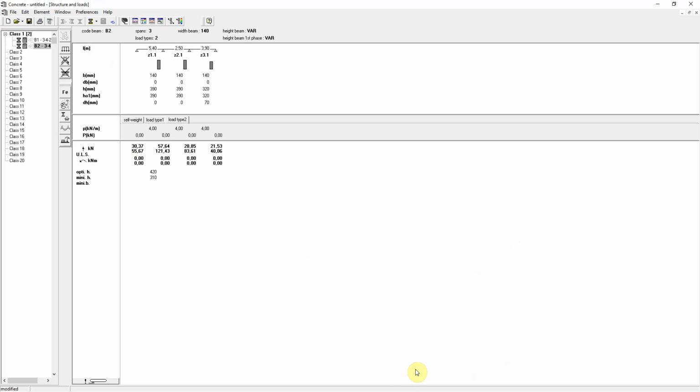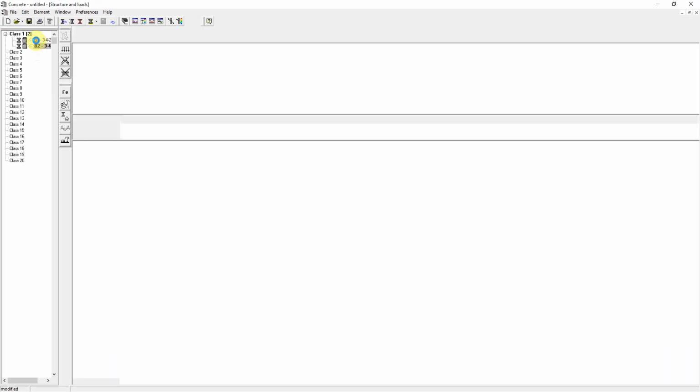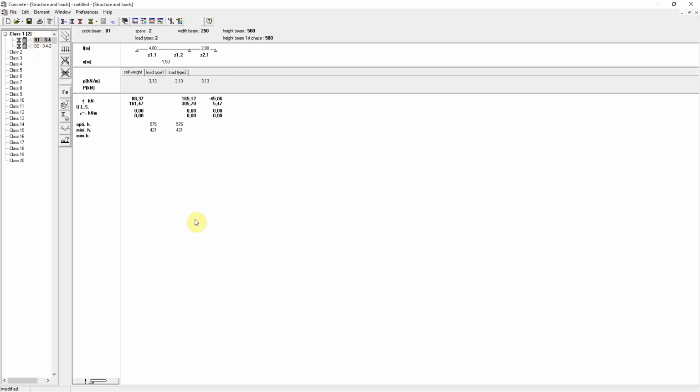I now also wish to add a third element, a plate bearing in one direction. The thickness is 240 mm. There are two spans of 4.5 and 7.3 meter. The loads are 3.5 and 2 kN per square meter. The settings of the active selected beam will be used as a template for the interactive questions procedure of the new element. Knowing this, I will make the first beam element active again because the plate has no height difference, and otherwise I will get questions regarding a possible height difference.